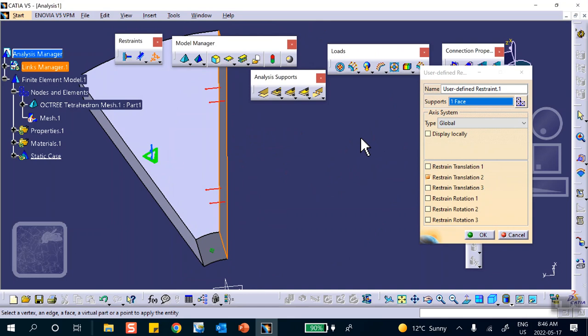But on the other plane, it's at 30 degrees. So you can't say y or x or z. You have to create a local coordinate system and select that as the displacement. Here, look. On this one, which is obvious and easy, I will actually put a surface slider.